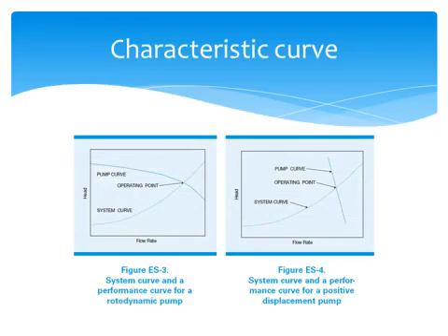The point at which the system curve and the pump performance curve intersect is the condition of operation. Typically, a system curve will require higher pressures for higher flow rates. Centrifugal pump performance has reduced flow with increased pressure. The slopes of the two curves are opposite. If the slopes are both gradual, the angle of intersection will be small.